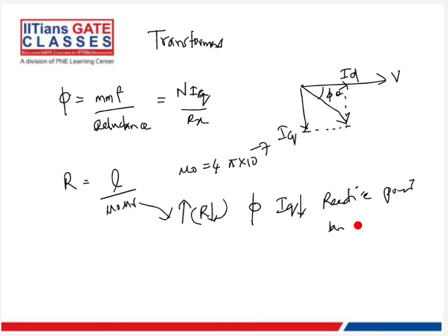the angle less means less reactive power burden on the system, right? So basically, what is Q? Q is equal to V I_Q, right? Reactive power is Q equals V I_Q. So if you are choosing the material correctly, which has high mu r, then R will be less, making the I_Q required for the same flux to be less, making reactive power to be less. Right?